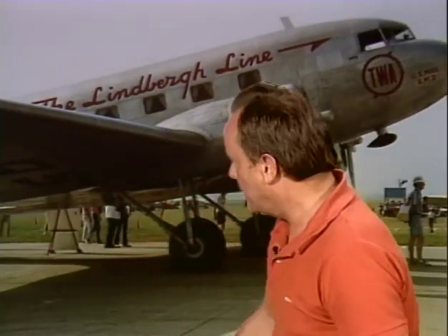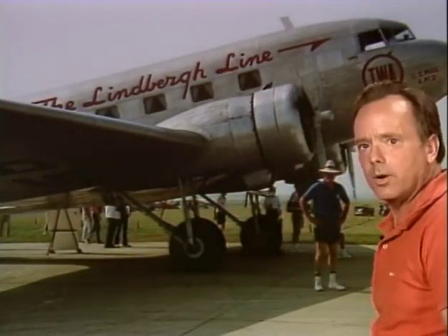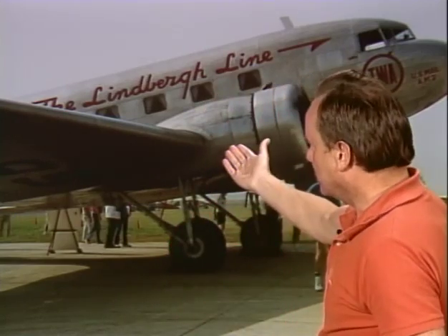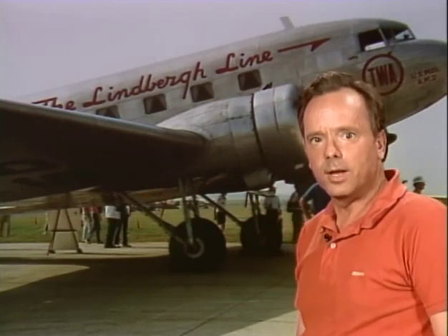Now let's talk about cable tension. Sometimes big aircraft like a DC-3 or a Constellation have a tension regulator in the flight control cable system. That's generally used in a large all-metal aircraft, and it's primarily to retain a set tension on the cable. So you might have a tension regulator in this airplane if you were flying a DC-3 or a Constellation.